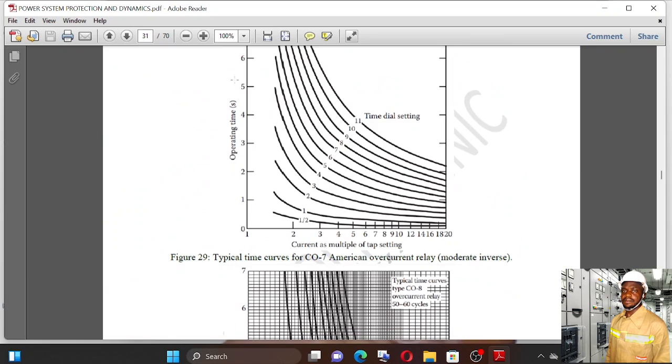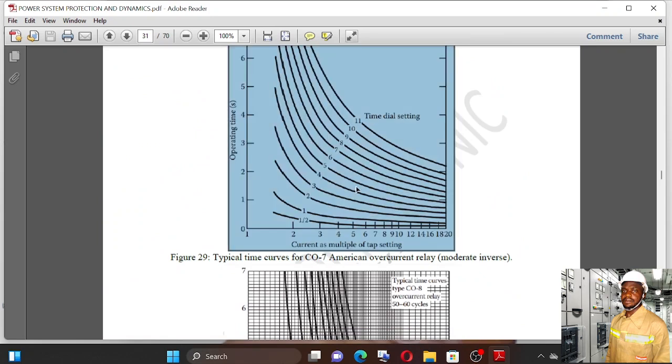Okay, here's the characteristic curve. We had 10. Since we desire a fast response, because normally the first relay is supposed to react, it's supposed to react instantaneously. It's the second relay if the first relay is not reacting appropriately. If the first relay is not reacting, the second relay has to take over. But the second relay will be taking over with respect to the time which the first relay was to react plus that coordination time. So the first one should react faster than the second.